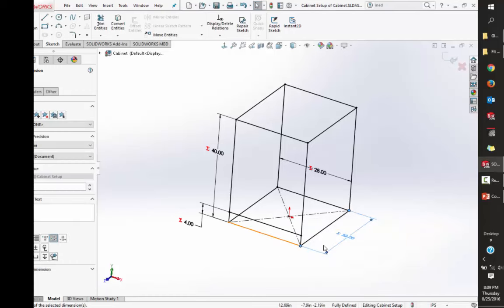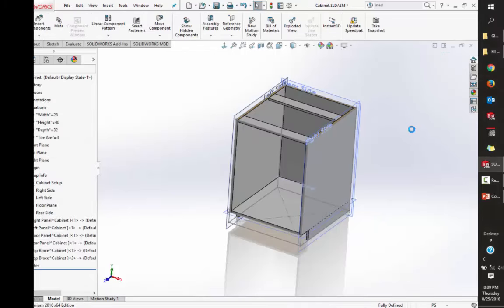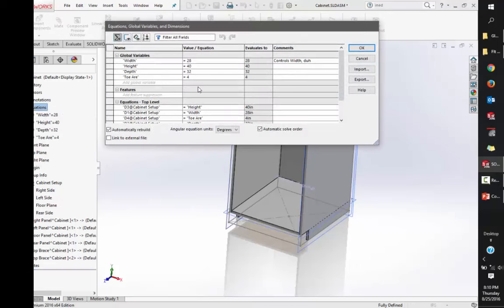Now, you'll see that it was slightly shifting a little bit as some of the numbers realign themselves. And that works out great. As soon as I get out of it, the cabinet's already sufficed itself. It's all good to go. So what I've made here is a single source destination. I get a new part number in, or I get a new project in. I simply come over to equations, manage equations, adjust the numbers as necessary, and I'm all good to go. That should be about how simple it is.